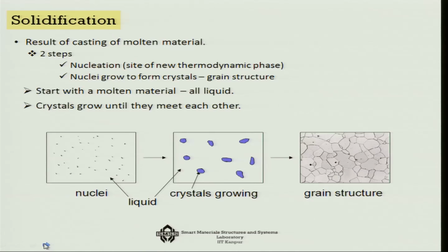So, the first point is about when the crystal is forming, which we have discussed earlier. Let us look back: from a liquid stage, through a gradual process of cooling, we get the crystal structure. If we make the cooling process very fast, then what we get is the glassy amorphous structure. Hence a very controlled, uniform, gradual cooling is a must in developing a crystal structure.